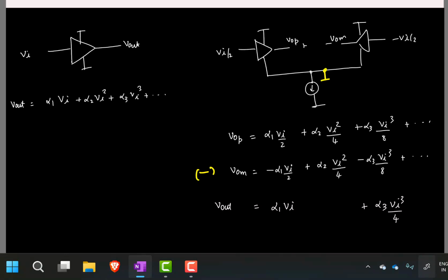What I'm saying is fundamentally you need non-linearity to get any power amplification, because like you told, the way we get amplification is we draw some power from the DC and convert that power to some other frequency, loosely speaking, right? And if you have only a linear circuit, you can't have frequency conversions.